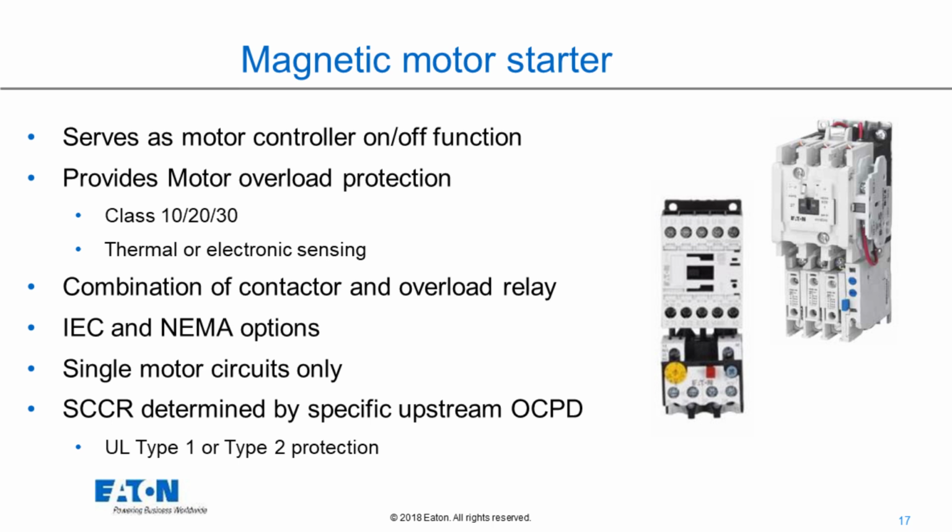The next device here is a magnetic motor starter. I remember the first time I saw an IEC motor starter, it was a long time ago. I thought it was a relay. It was so small compared to a NEMA back then. But these devices serve as a motor controller, on-off function. They're typically controlled remotely from like inside of a motor control center.